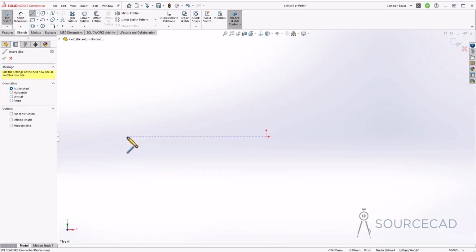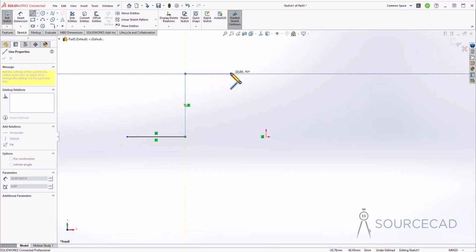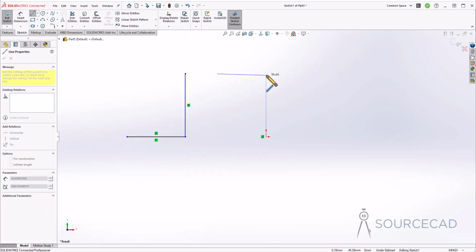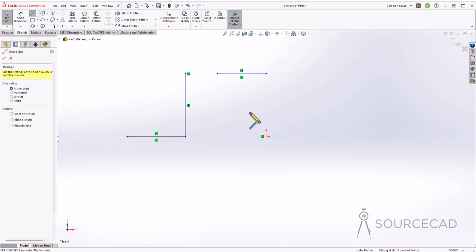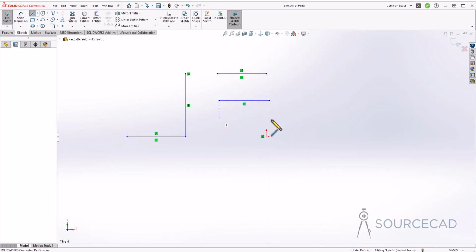When making a line, you'll simply get this kind of workflow. Select the line. Now if you want to exit, simply press escape and start over again, and the line command is here again. Now if you want to cut one single step, that's exiting and starting it over again, then you can simply double click, and now not only the command will exit, but it will also start the line tool again. So here we are. Once again, let's say we want to exit and make another horizontal line, then double click, and there we are back to this.